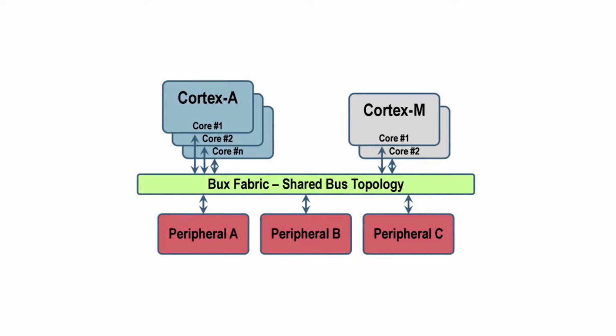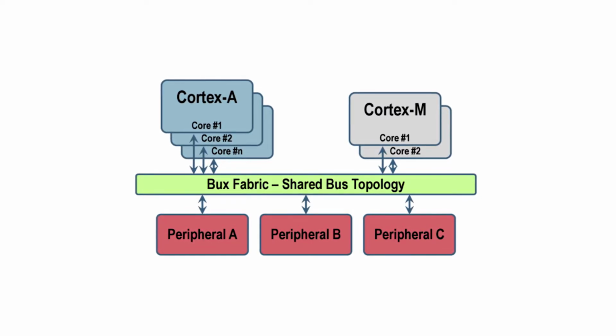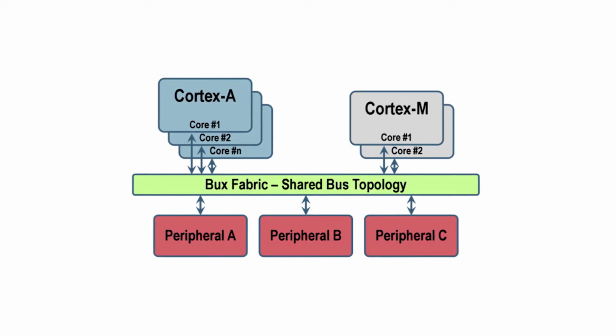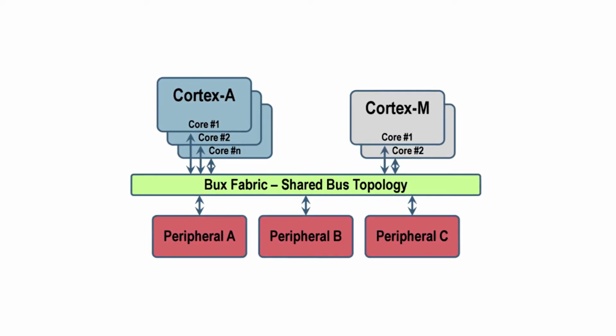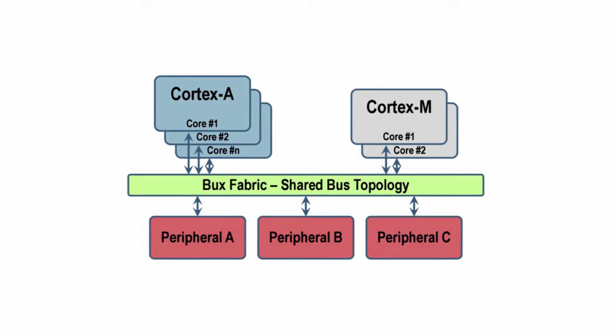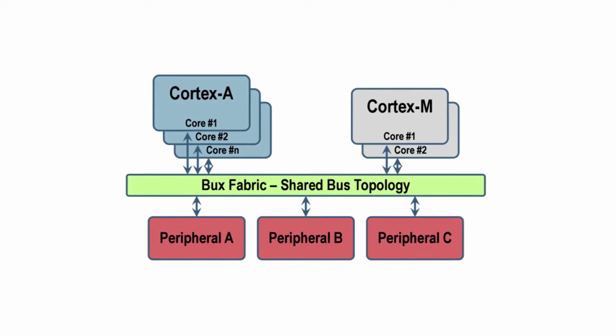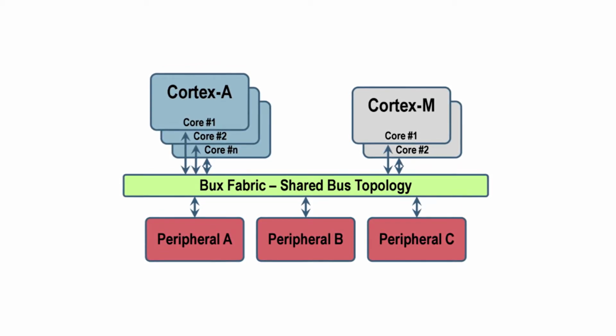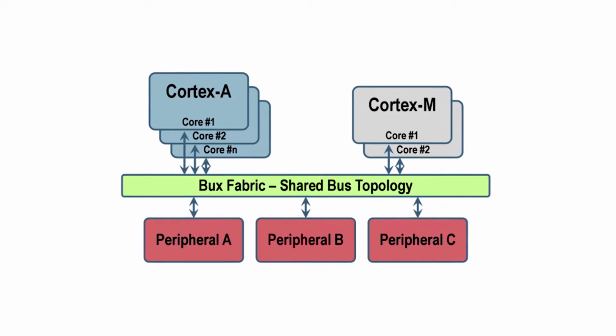Before we continue, I want to give a quick overview of what HMP means specifically in the i.MX world. Here we see a schematic illustration of an application processor with one or more Cortex-A cores and one or more Cortex-M cores. This is heterogeneous because Cortex-A and M cores are a bit different and optimized for different things.